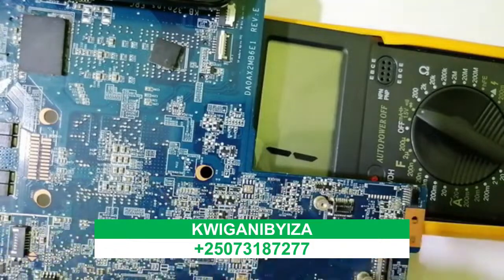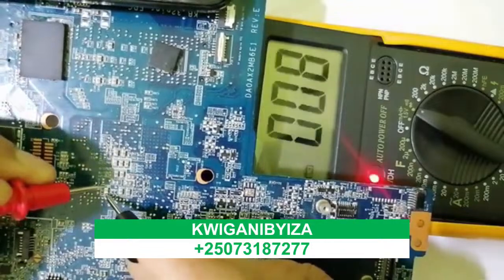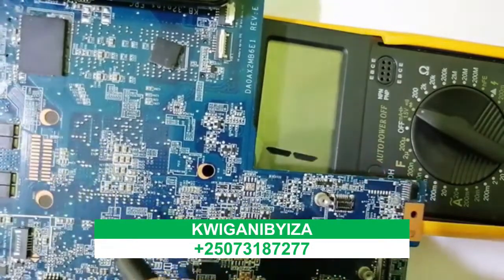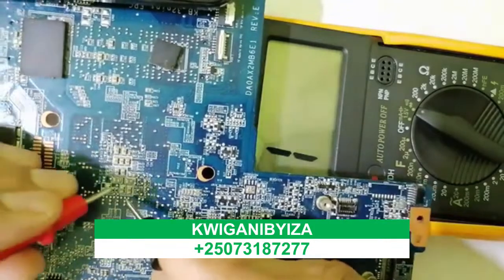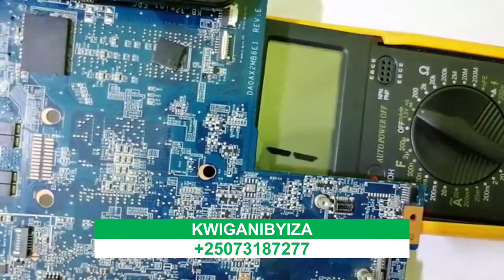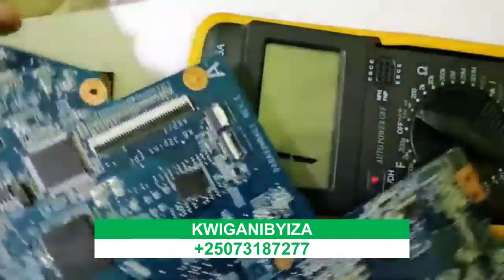So let's check any ceramic capacitor. Let's check this one, for example. Do you see we get a very low resistance in the multimeter? Let's check this one also. As you can see, this is a short. No, this is not a ceramic capacitor.